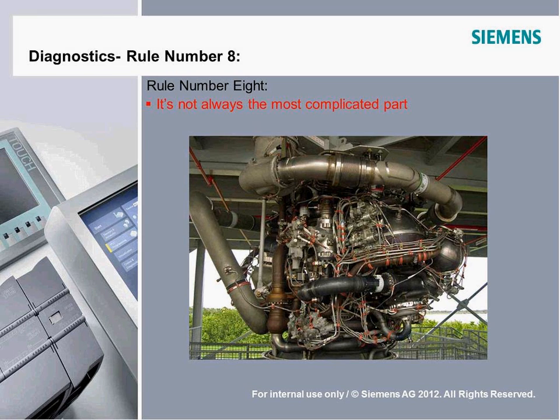And finally we zeroed in on that module replacement. The real fault was the 0 to 10 volt module had gotten some hydraulic fluid in it. So there was an instance where the fix by replacement didn't help. And in fact, what should have happened there is that when it didn't work, he should have gone back and put the original module back in place, and it would have made my job a lot easier. In any case, that brings us to rule number 8.